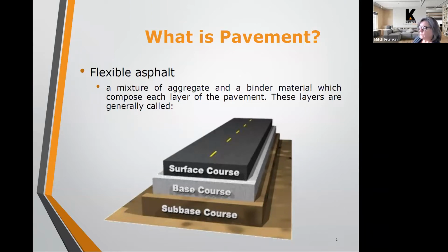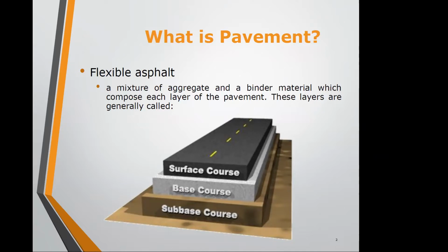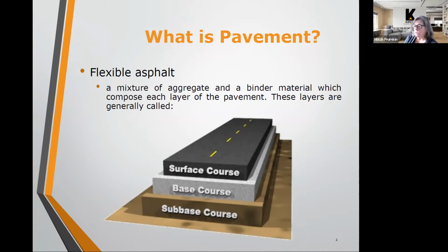It's made of several layers. There's obviously the earth underneath, then the sub-base course, which oftentimes is an aggregate, another name for stone or sand, or a mix of stone, sand, and stone dust. Sub-base courses are oftentimes what's called a dense graded aggregate. It's a mix of several different sizes of aggregate that, when compacted, is for the most part waterproof and provides a very stable subbase for pavement courses on top.